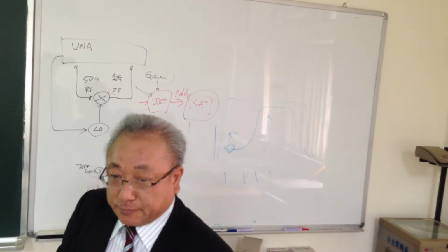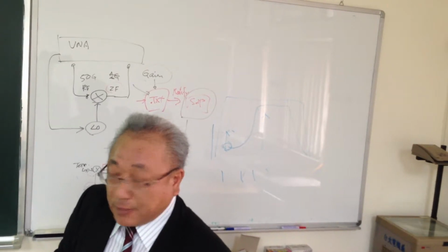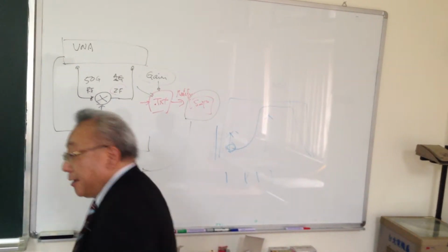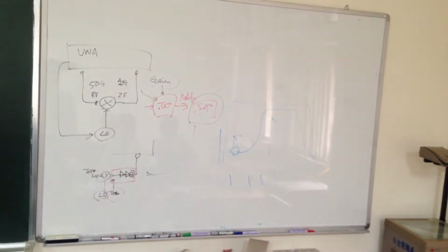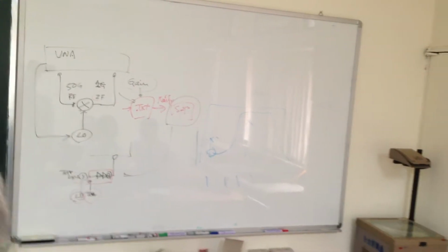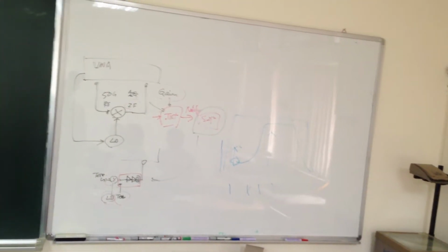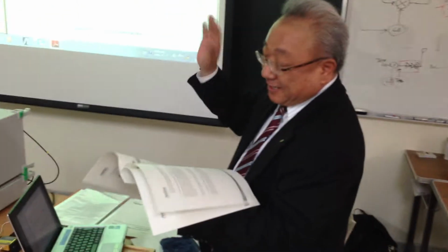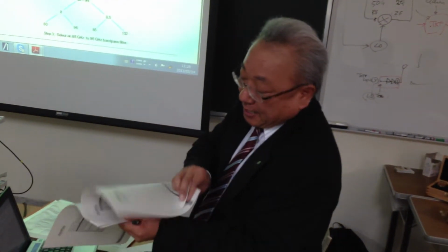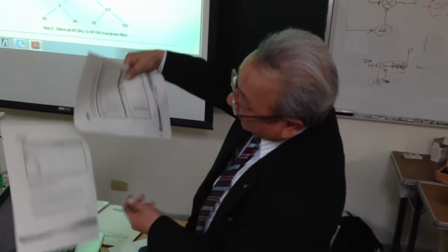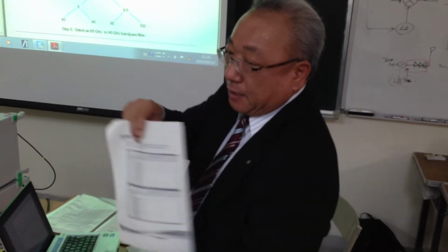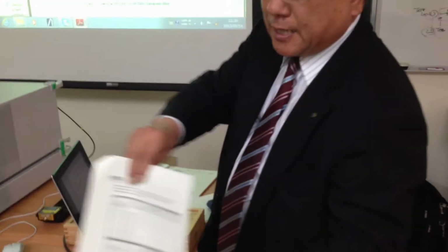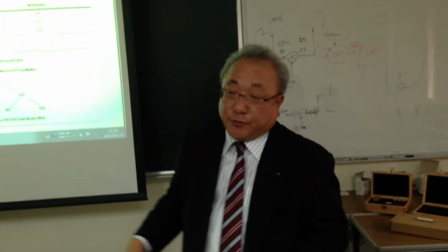So how do we define the S-parameter file, S2P file? We also include the S11, S22. So we have to make an image file first, then put the conversion gain into that image file, then transfer it to the S2P file. That's kind of the procedure. We can supply it already.